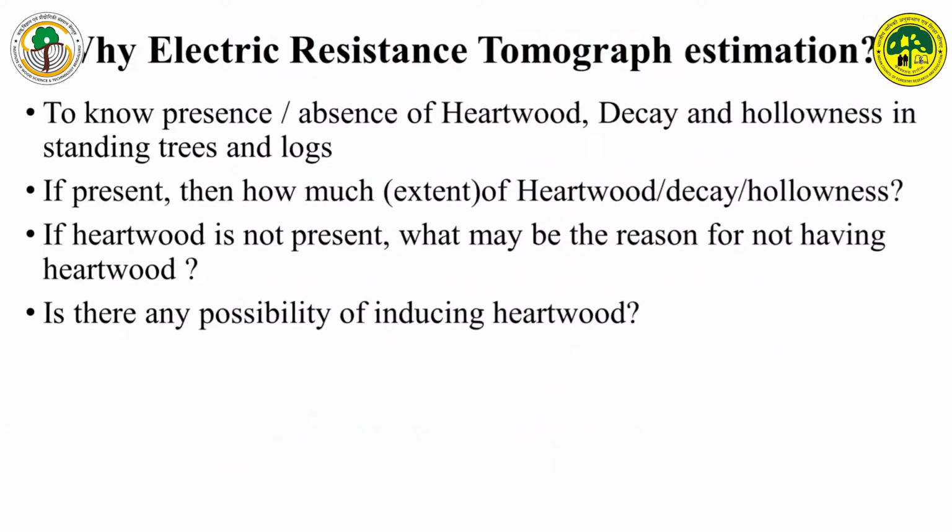Why is this electric resistance tomograph estimation required? Because it tells about the presence or absence of hardwood, decay, and hollowness in standing trees, and even in logs. If present, it will help us calculate the extent, because it gives a three-dimensional structure when we measure. So this helps us estimate the extent of hardwood, decay, or hollowness.